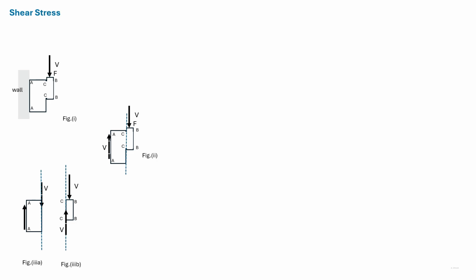Here we look at a case where only shear stresses are acting. So this is a bracket attached to a wall on which a force P is acting. To start with, we'll look at the equilibrium of the whole bracket. So if there's a force P acting, there must be an equal and opposite force P due to the wall, as shown.